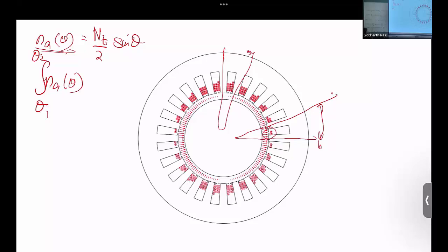So if you take this example, we have +2. We have one conductor coming out of the slot, going 180 degrees outwards to the other side, and then going into the slot, and then coming out, doing this twice. Then the same wire goes to the next slot and does this, whatever number of times the value comes out to, and we keep doing it until we come back to the final slot. We start off from the first slot and call this a terminal, and wherever we end, we call that the neutral terminal.